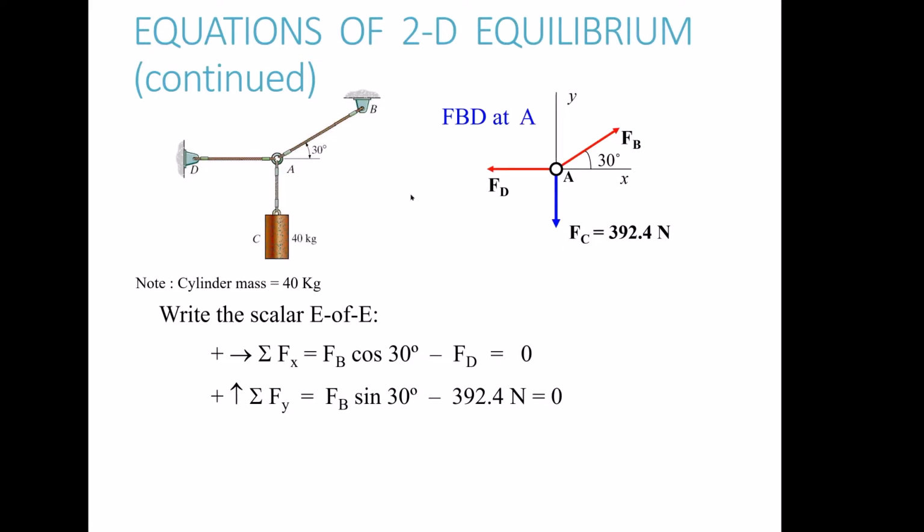This problem's not too hard to figure out. Which is it, under compression or tension? That's pretty straightforward. It's going to be under tension. It's going to be trying to pull it out this way to the left. And the only point of something like this is that if your answer for FD ever becomes negative, if an answer for a force is ever negative, all it really means is it's in the opposite direction of what you thought it was.